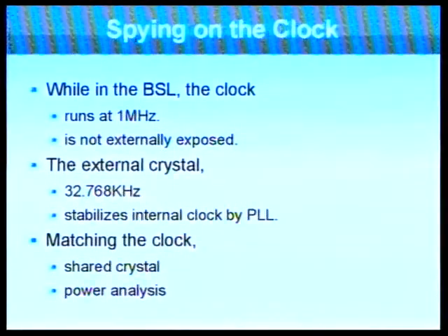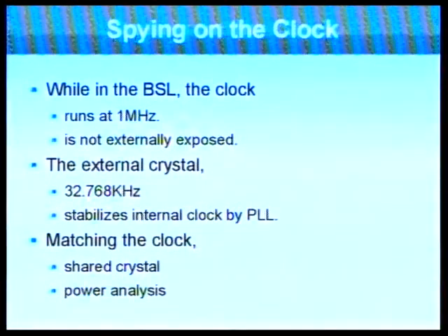So in doing that, you can break into a BSL that has been disabled. If I know the password, but you've turned off the BSL, I can still get into it. Another issue is that it's difficult to time the glitching if you don't know exactly when the clock pulse will hit. And the clock is only exposed if you choose to expose it. The external crystal is at 32 kilohertz, and then a PLL multiplies that frequency for the internal clock. And even then, the external crystal needn't be used. It's not powered up when the BSL is running.